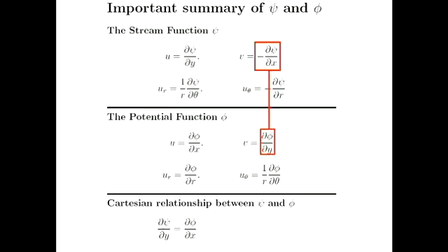And there's a similar relationship if I equate those vertical components of velocity. So d psi dx is equal to minus d phi dy, or minus d psi dx is equal to d phi dy. There's an obvious relationship between those two functions. We've kind of shown that because we've shown that they're perpendicular to each other.